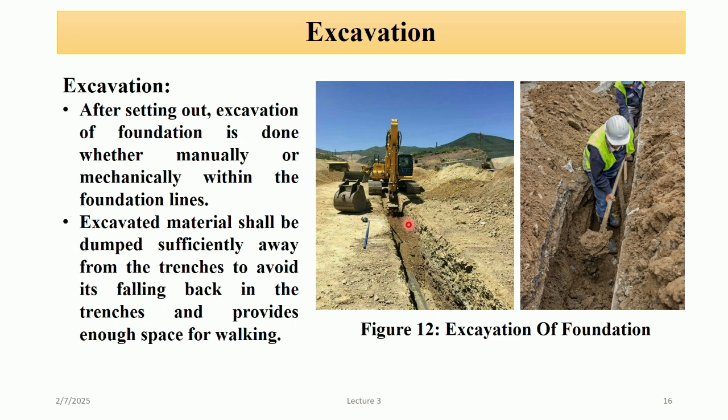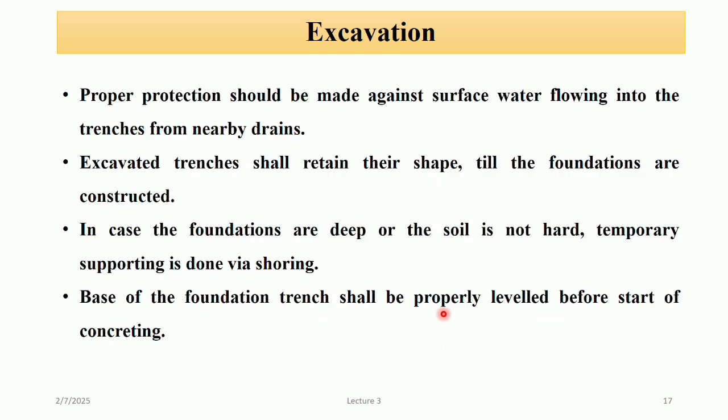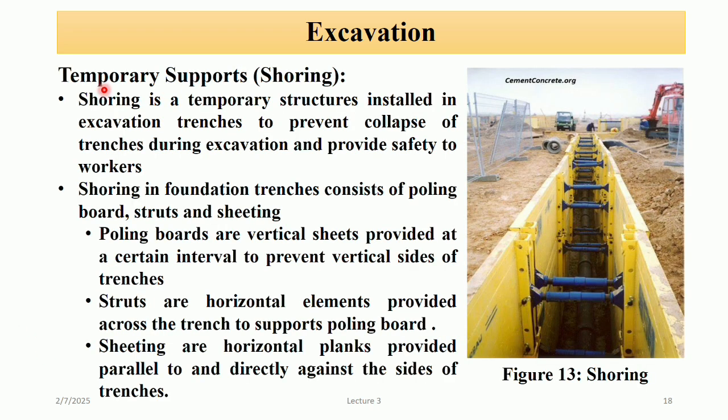And we have to protect the trench against surface water flowing in, and till the foundation is constructed, the shape of the trench should remain intact. For that, if the foundation is deep and the soil is not hard, we have to provide a temporary support in order to retain the shape of the trench. And we have to properly level the foundation trench before the start of concreting. A temporary support is also called shoring.